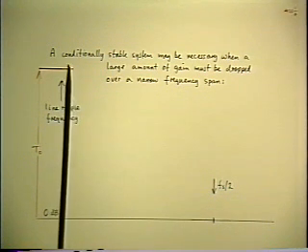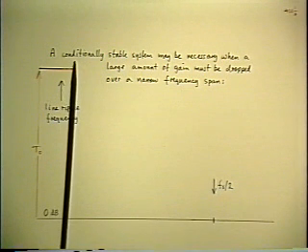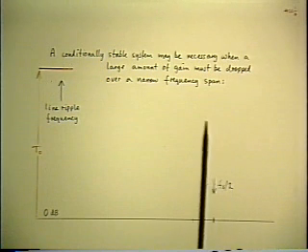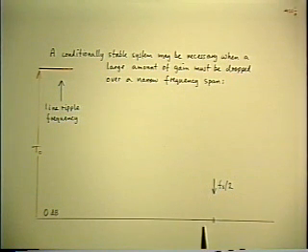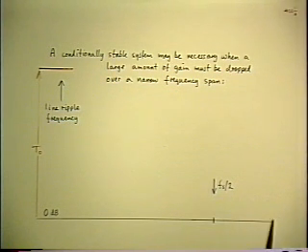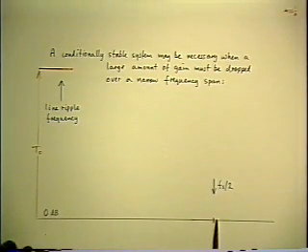So, a window is now defined. The bottom of the window is 20 kilohertz, and I have to keep 40 dB up to that frequency, but I now have to impose another side. I have to impose a maximum frequency at which I can allow crossover to occur in order to keep control and not have the parasitics take over from my design, where the parasitics are something I can't do anything about. So that defines a window. Call it this frequency here.